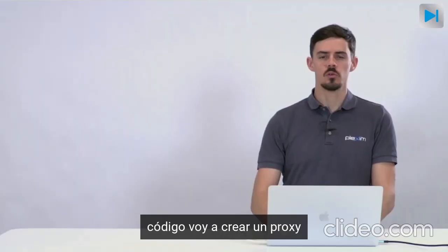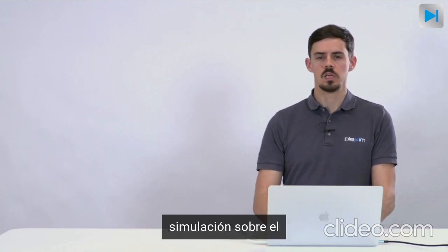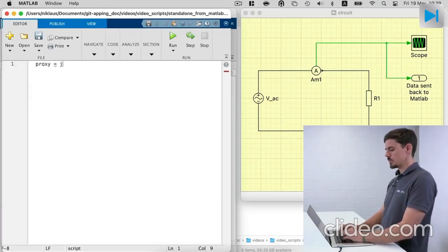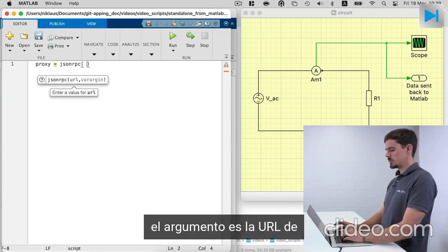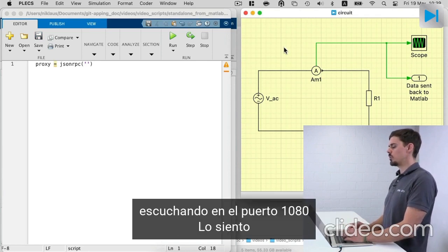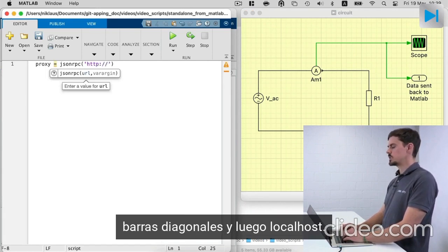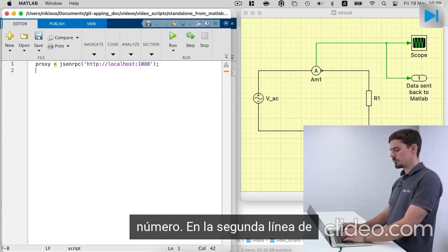And in the first line of code, I'm going to create a proxy object that calls the PLECS Standalone simulation over the JSON RPC interface. So it's called JSONRPC, and then the argument is the URL of the server. And in our case, this is running all on localhost, and we are listening on port 1080. So we write http://, and then localhost, and then specifying the port number.